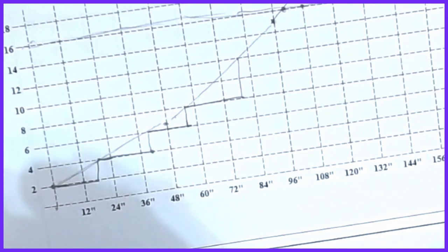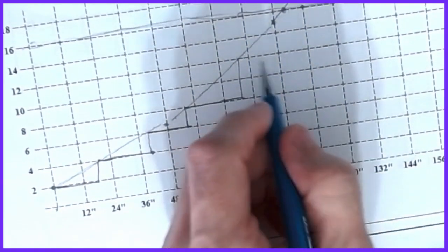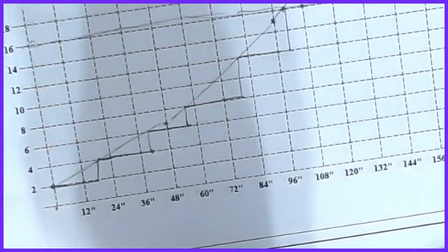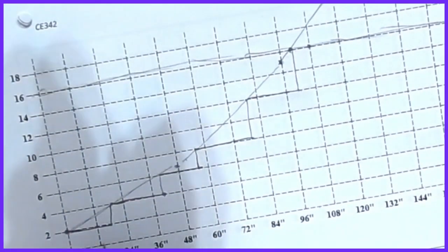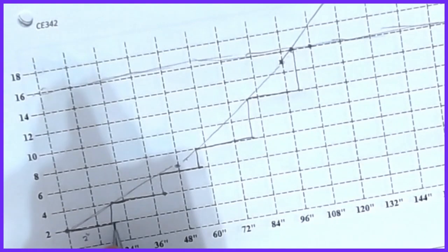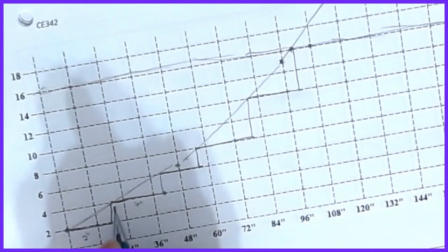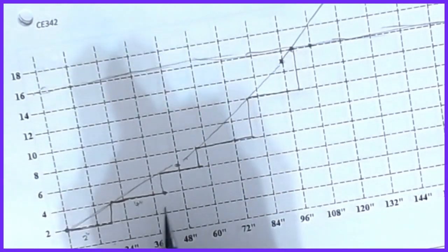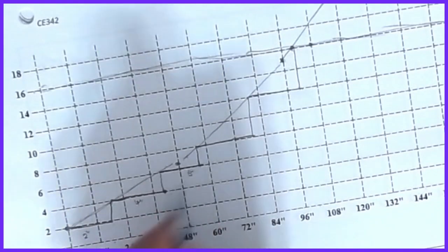Something that looks something like that, right? And then so forth and so on. And then at this point, I go 12, and I go all the way over to 16 at this point. And so that would be your spacing curve. So there's a 2-inch curve, and this says I go to about 18 inches. And then this is my 4-inch spacing, and I go from the end of that one to 30 or whatever it scales out to be. And this is how you build these curves.